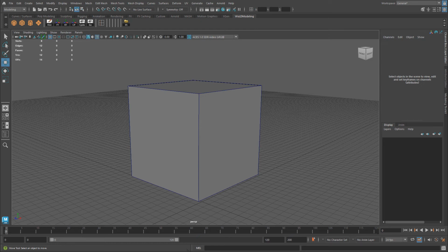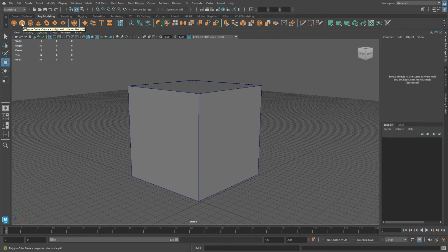Start a custom tool shelf. By default, when you have Maya installed, it will come with the default set of shelves that you can use to get access to some of the most commonly used tools in Maya. So for example, right here, if you switch over to any of these tabs, such as Poly Modeling Tool Shelf, it'll give you access to some of the commonly used modeling tools right away. So instead of going to some of these drop-down menus, they will be placed as icons right here for you to use. So in the Poly Modeling one, the first few have primitive shapes already added.